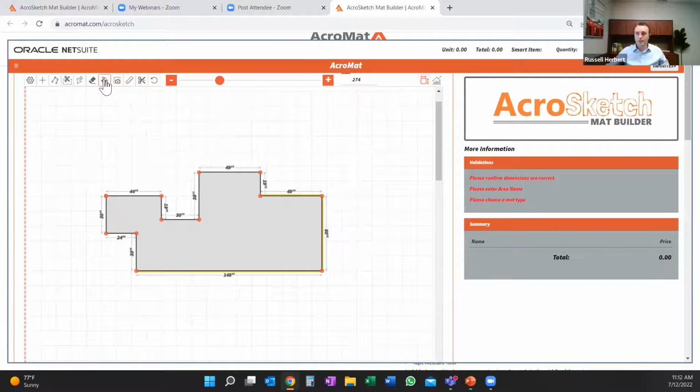If you click it one more time, it will turn black. Sometimes you don't need a yellow bevel, you just want a black bevel. So you can see what happens when you add that one as well. In this particular case, we'd have a yellow bevel around these 3 sides. We'd have a black bevel around these sides, and the remaining sides would have a square edge with no bevel. If that's going to be up against a machine or piece of equipment, then that's usually a helpful thing to do, is to remove that bevel on the inside edge.